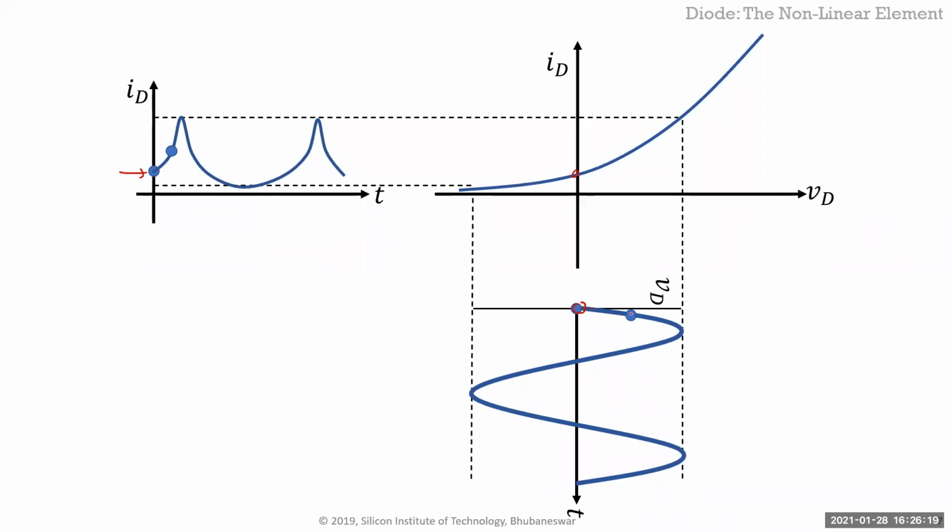here. And if the voltage is like VDD over 2, where it's a sine wave at pi by 4, then that's roughly here, which I trace back here. That's this current. And I go to the next one at the peak, it's this current, and then back here and so on, right? So as you're going through the sine wave, that's the current you're getting, right? So you can see you're not getting a sine wave. You're getting this distorted signal.